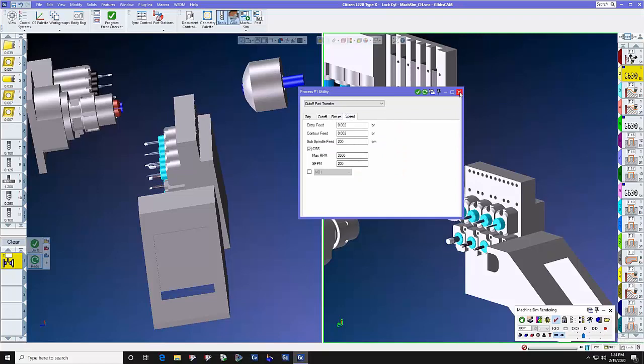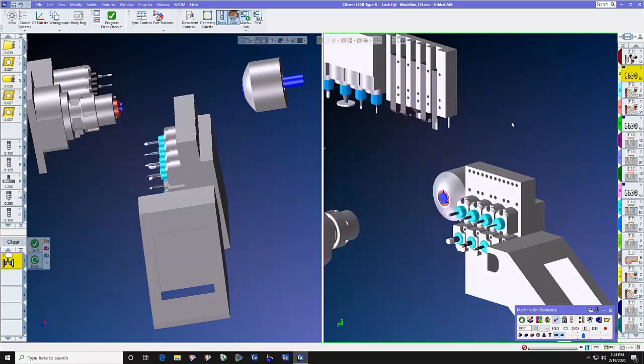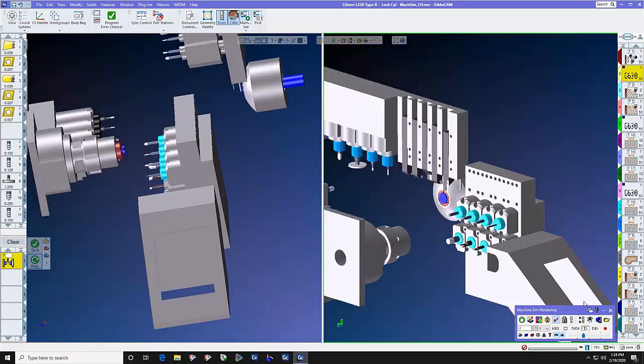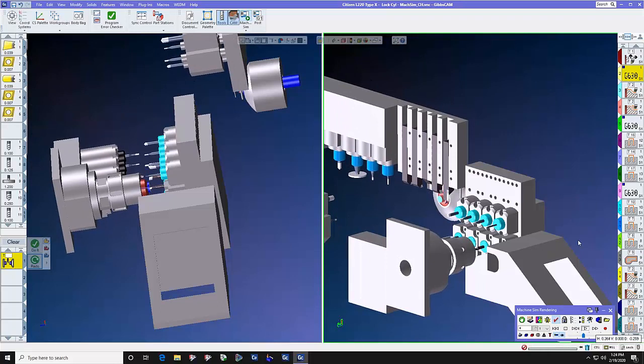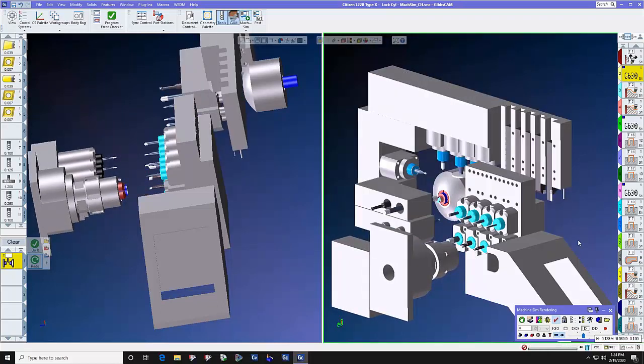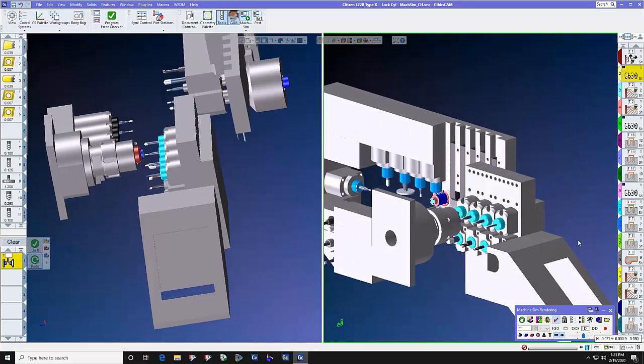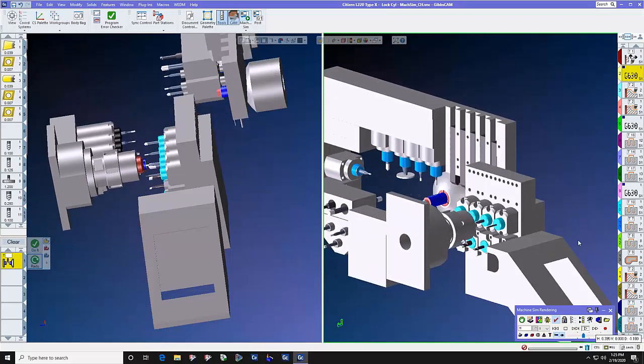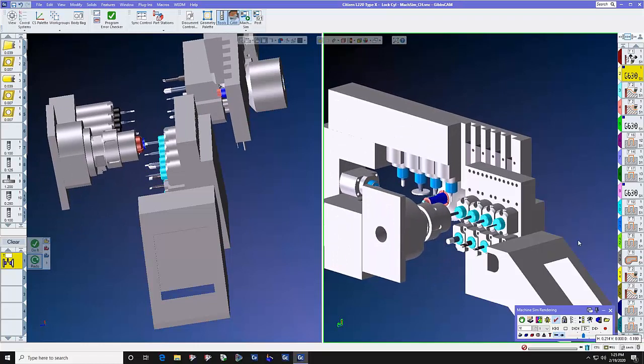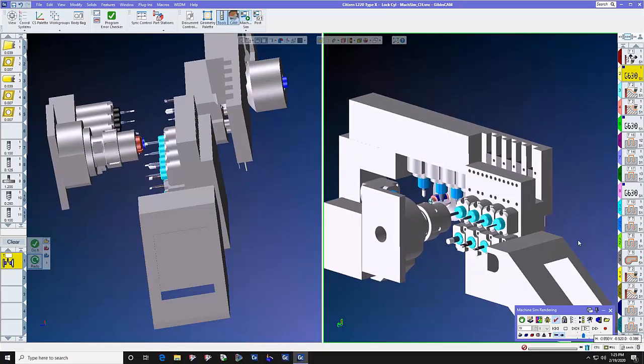And that is a cutoff part transfer. Automatically, when we do a cutoff part transfer, you will see that the appropriate axes physically get out of the way so that the sub spindle can come in, the parting tool can do its job, and nobody has any collisions. Again, this is a function of MTM level 3.